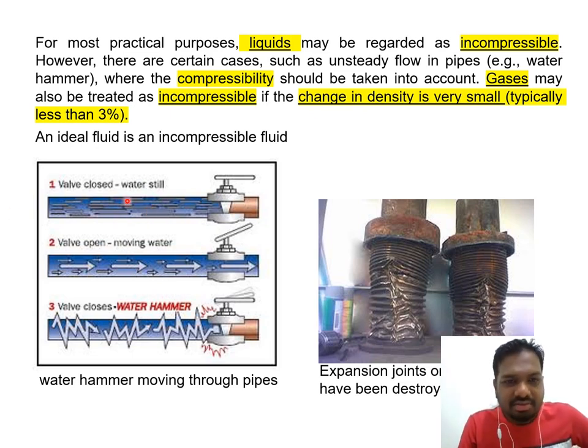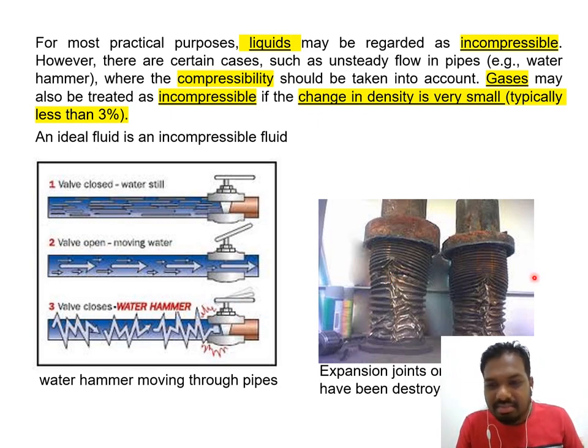But this is a condition where water is still at no pressure and the valve is closed. Then suddenly you open the valve, so water starts to move from this point to this point, and suddenly you close it again without warning. Water is flowing, pressure is entering, and there is a water force. Suddenly you close, then what will happen? It will cause a water hammer. This is the physical water hammer or steam hammer that happens in the field.